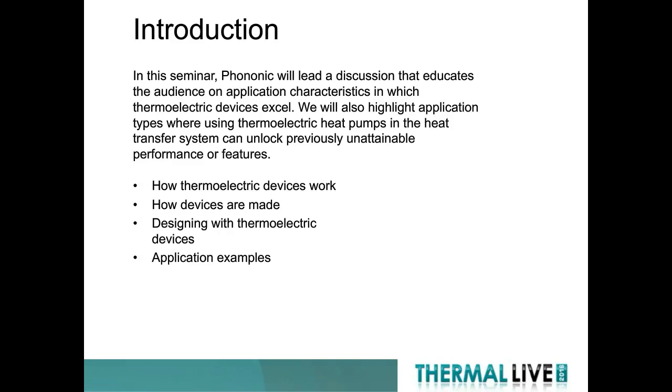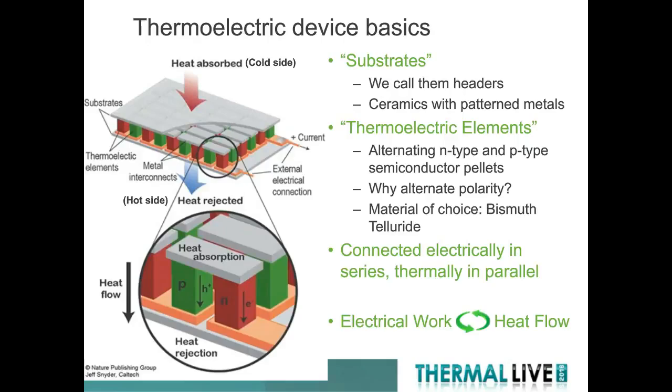Sure. Hello, everyone. Thermoelectric devices are, in essence, solid-state semiconductor-based heat pumps. They consist of substrates, we call them headers, on either side that act as your heat exchange surfaces, and on the inner side of the device are patterned metal traces to act as current carrying elements.